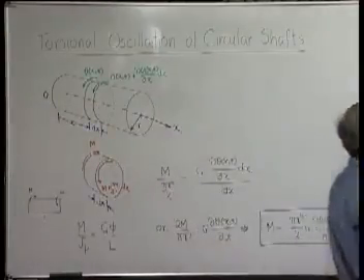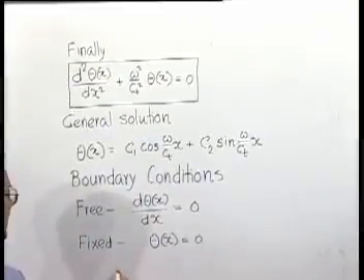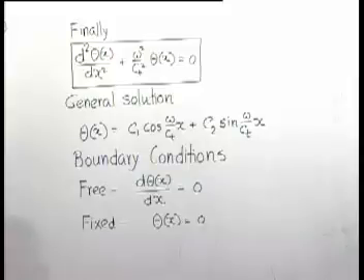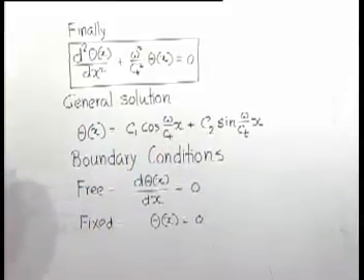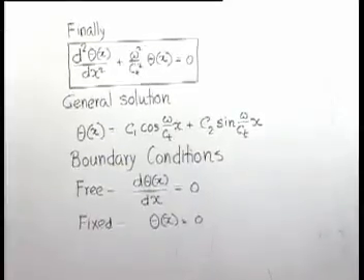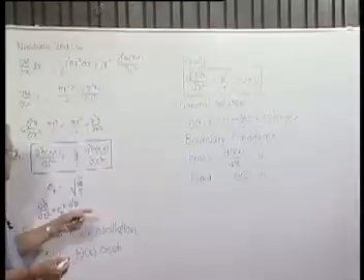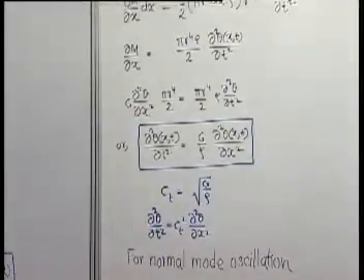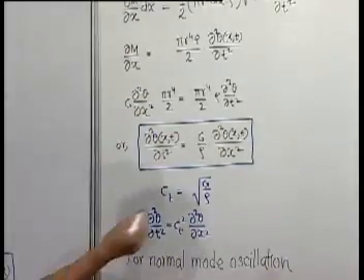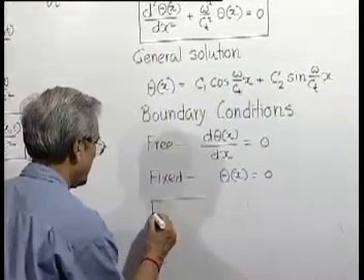So similarly, we can proceed to solve various kinds of solutions, and we will get exactly similar expressions, only here that C will be replaced by Ct, whose value is equal to square root of g by rho. In case of longitudinal wave propagation, it was square root of E by rho. So we will not repeat that. Rather, I think we would like to solve an example. So one can easily solve various types of conditions.